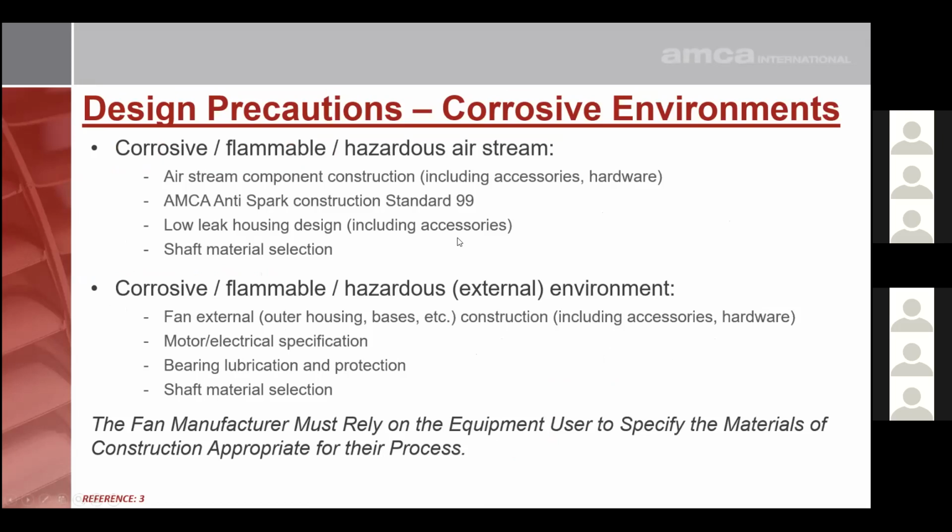So what do we look for when we design these fans? We first need to understand if only the airstream gases are corrosive, that is the air going through the fan, or if the fan is placed in an environment that is corrosive. If the fan has to be designed only for a corrosive airstream and not the external environment, we then look to see if the gas is only corrosive or if it is flammable and hazardous. The reason for this is if it is flammable, we would need to consider an anti-sparking device. If it is hazardous, we would need to consider a low leak design.